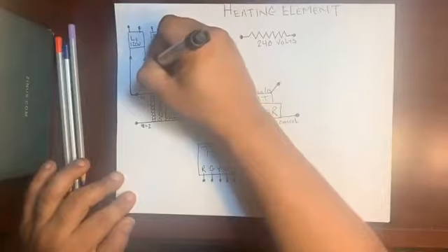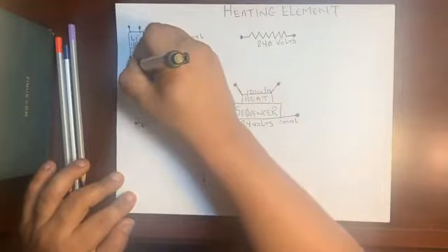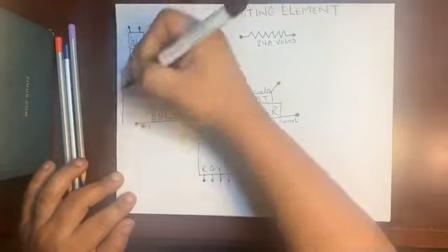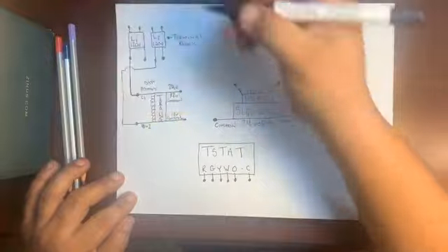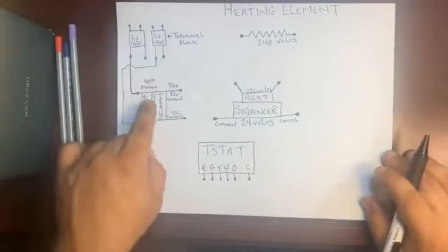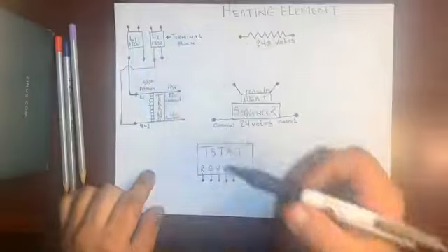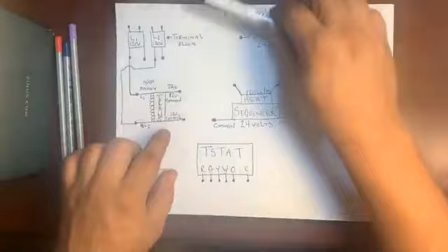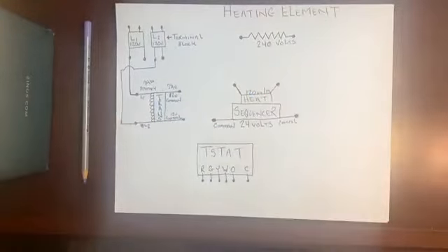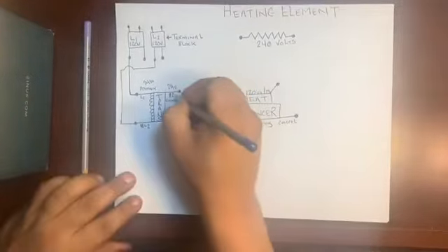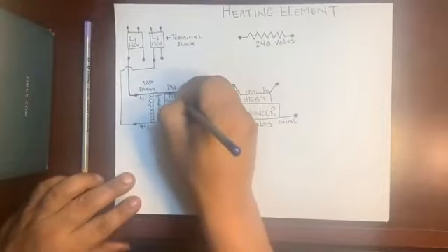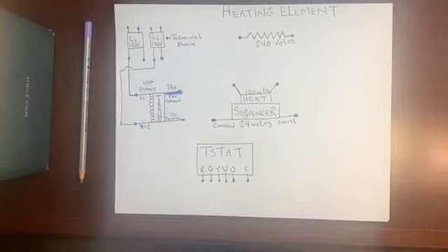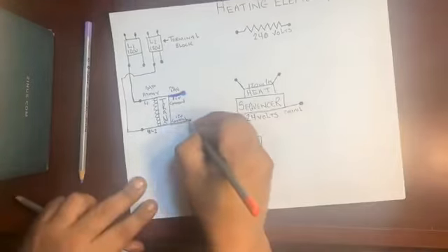Bring this down, crossing the line, make your half loop bridge. Very good. Come down and connect in over here. Primary side has 240 volts, 120 on L1, 120 on L2. Now we're gonna produce 24 volts. We got our 24 volts, we go to our secondary side, then we use colors. As we discussed, 12 volt common is going to be blue for the purpose of our diagrams, and 12 volt control, red.